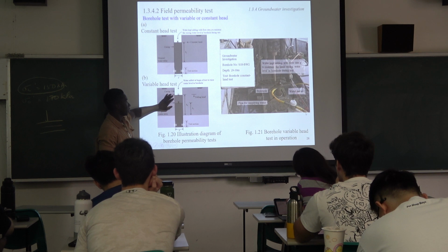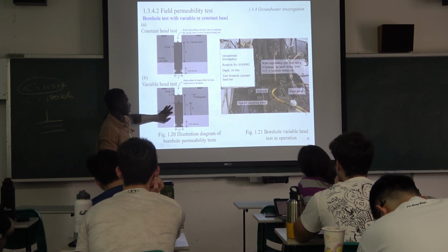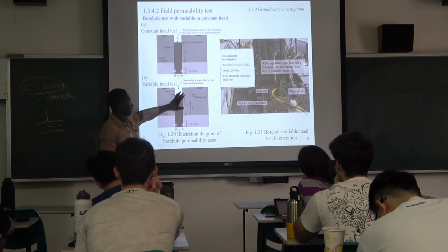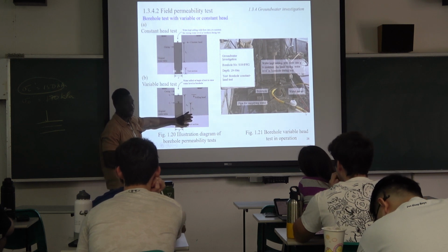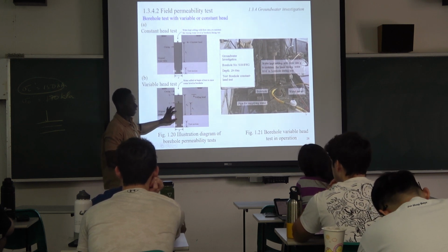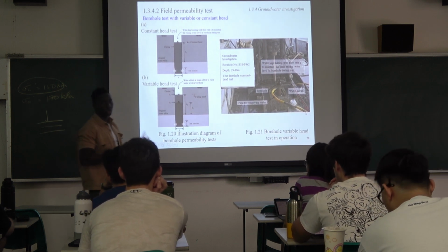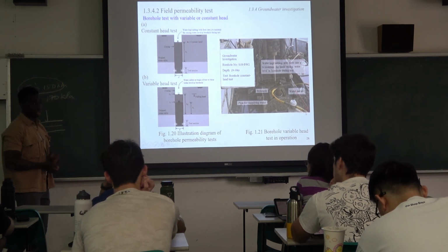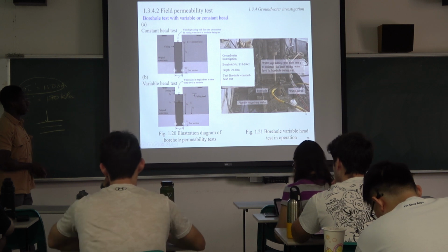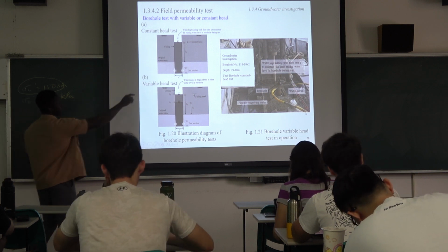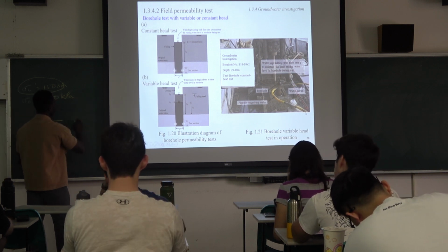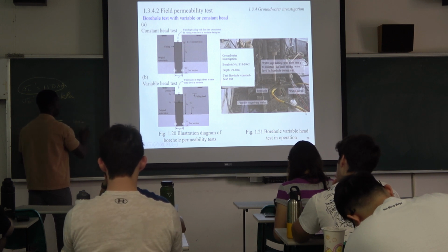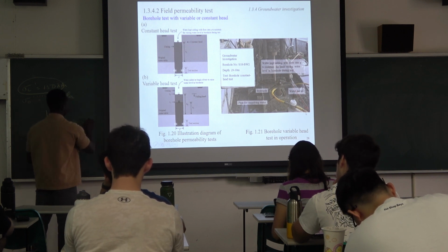Okay, and this is the time at 0. The time at 1 is when you add water up to this height, and then the initial height, and the new height at time equal to 1. So you can use this to calculate the hydraulic conductivity of this soil. For example, if H1 is already about 10, and then at this point it is 5 meters.